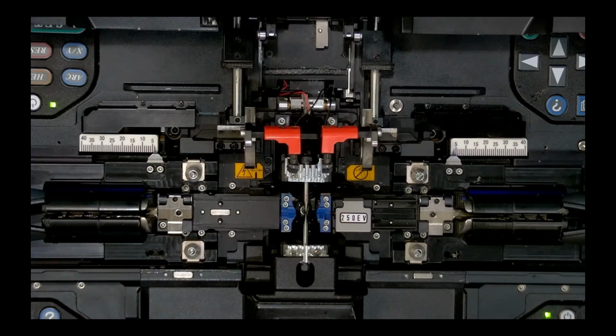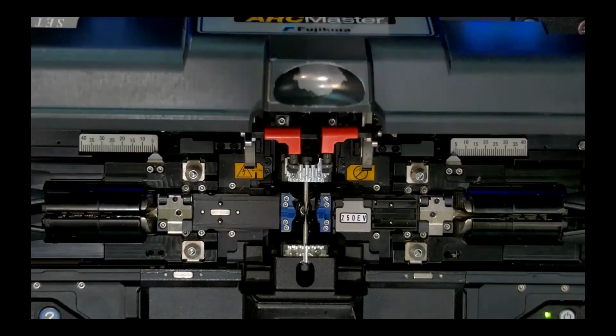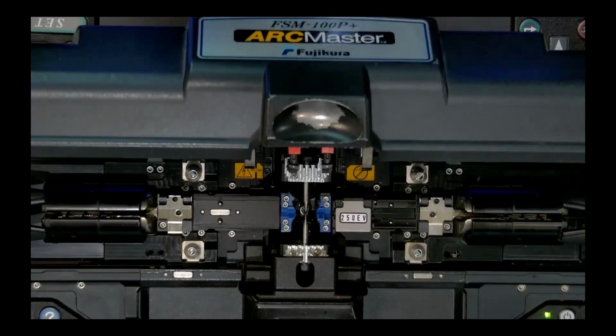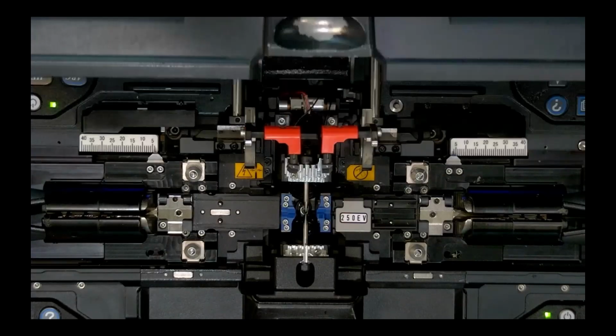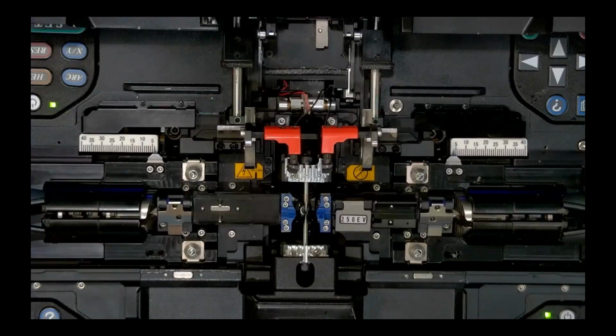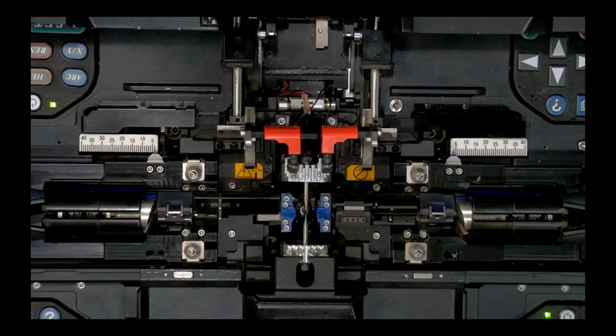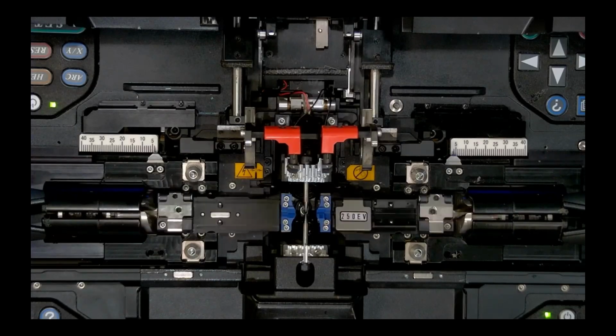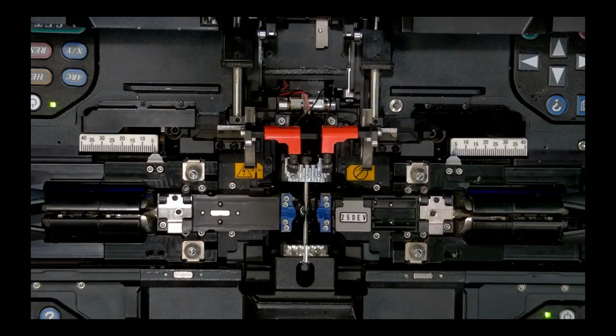And then the last thing I want to mention is your theta unit here. This is what will physically give you the ability to rotate the fibers, right? So if I back out and go to my motor drive function in the splicer, I can turn both of these, right? And this will allow you to get PM alignment capability using the functions of the splicer, right?